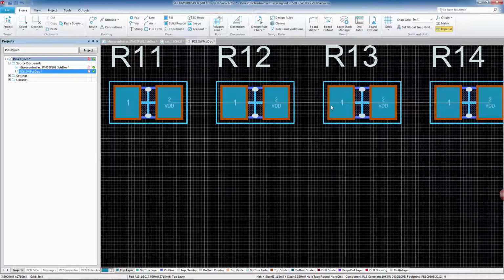So I really recommend that you edit that connection matrix in the project options, and you configure the unconnected columns and mark those boxes.